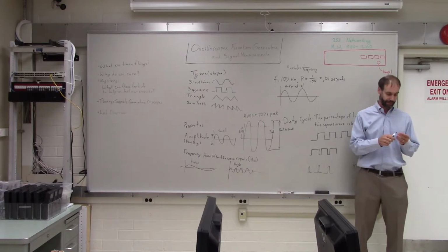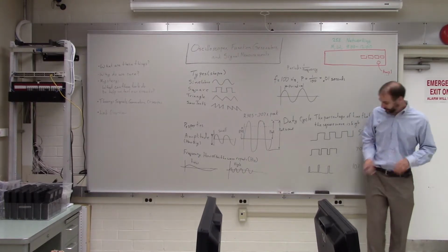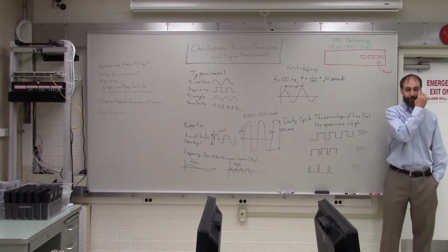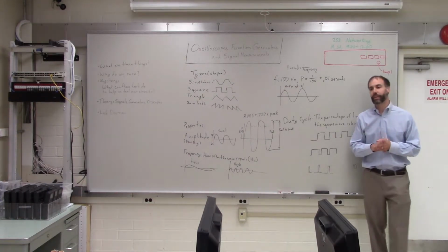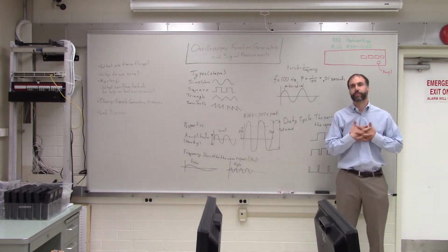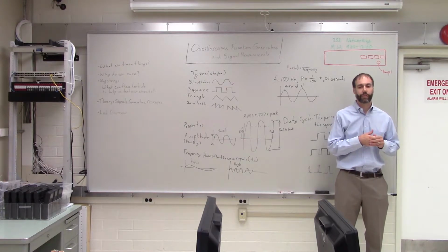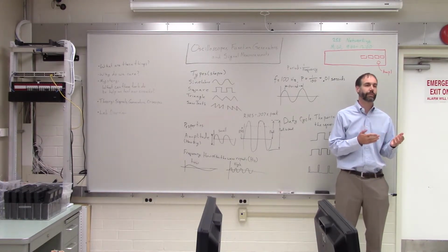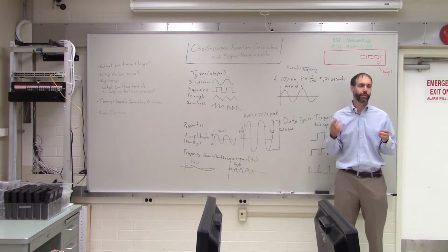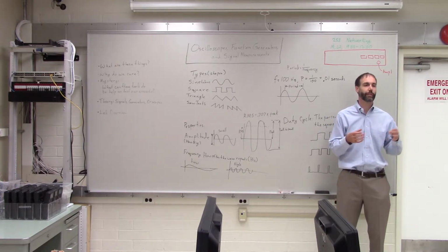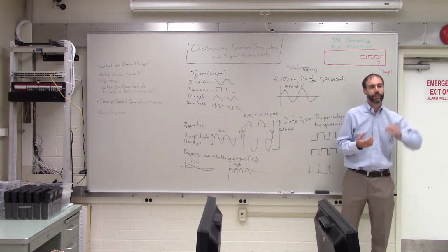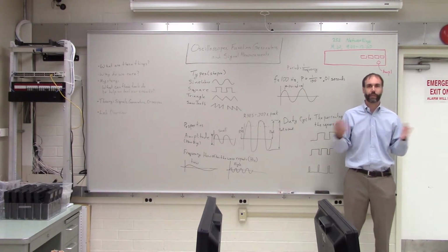Why would you need the RMS? That's a good question. It's sort of a funny thing. Basically, if you have a 10 volt DC source and you put that into a heater, and then you have an AC source that's 10 volt RMS and you put that into the same heater, they generate the same amount of heat. So it's sort of like the equivalent amount of power between AC and DC.